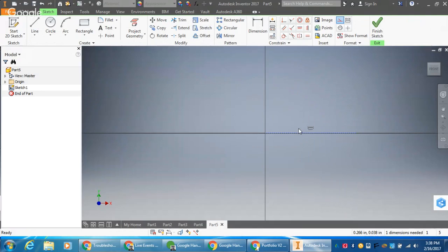So there's a bunch of ways we can do this. One of the things you see is that we have a typical radius that we fillet at the end and smooth over all the edges, which means I can box everything off. So I'm going to start and give myself another line to work from, and again, just make sure it's horizontal. The length of that line we don't really have to worry about right now, but you could say the length can be the overall width of the wheel if you want to make it a little easier for yourself, which is 0.25. This is going to be the overall width here.